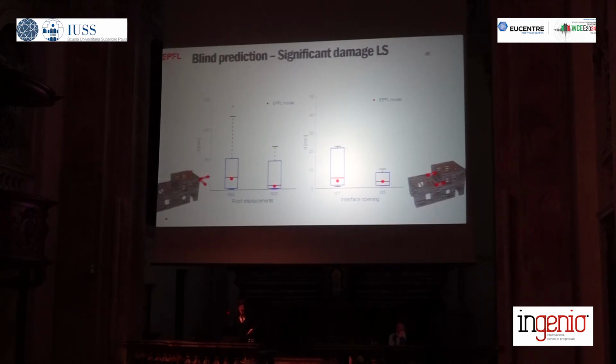and we came a little bit down to earth when we then saw the experimental results, which were completely not where the median prediction was. So here are the experimental results in green. Of course, the experiment is never exactly what we had as input, but we made a comparison. I think it's a reasonable comparison to be made, and the discrepancy doesn't come from the discrepancy between input and output, I would say, or not the largest part of it. So what you can clearly see is that the majority of participants, including us, really underestimated the displacement demands considerably.